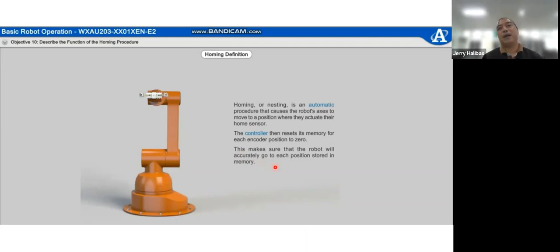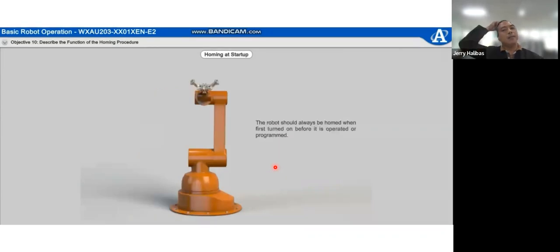Okay? So the movement of the robot is relative to its home position. If this were geometry, we call it the origin. These are the axes, right? This is a Cartesian axis, so the origin is 0, 0, 0, XYZ. That is supposedly the home position, if you're going to make an analogy with a program.